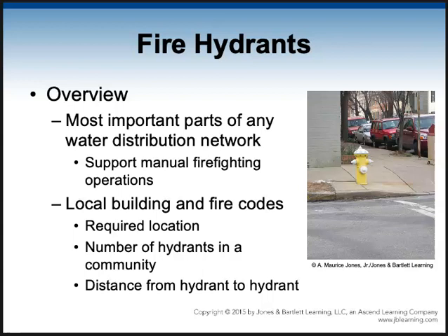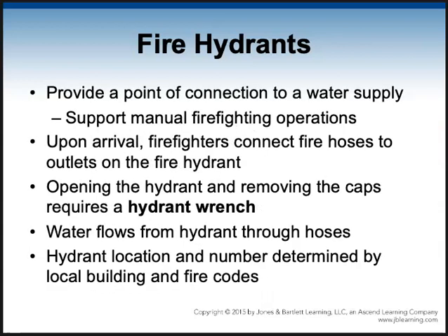Local building and fire codes are going to require the spacing, the kind of hydrants, the number of connections on each hydrant, and that distance from hydrant to hydrant. Now, the local cities can get stricter. They can't get more lenient than the state. The state will have standards in the California Fire Code, but local counties and cities can make it a little stricter if they choose to, as we talked about before. Fire hydrants provide a way to connect for the fire engines and for firefighting operations.